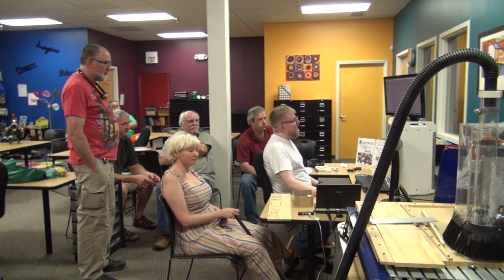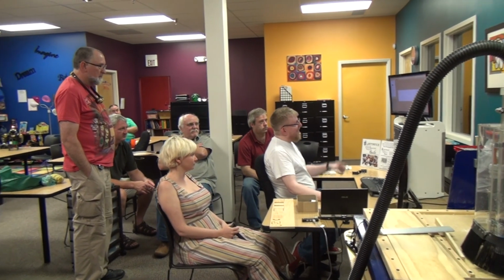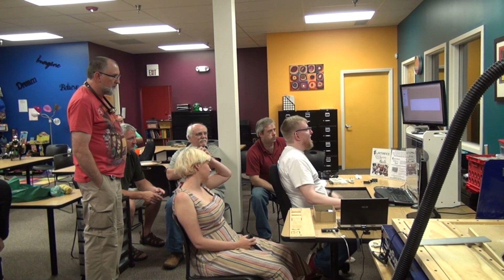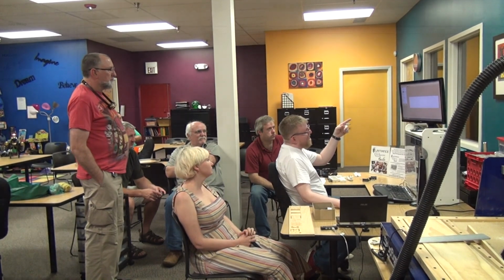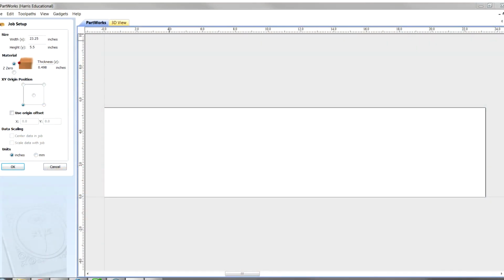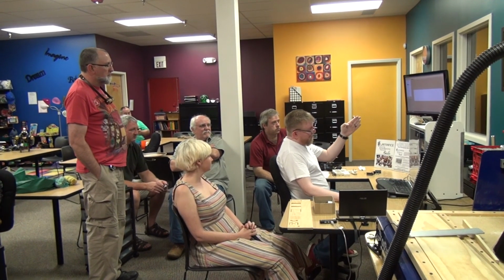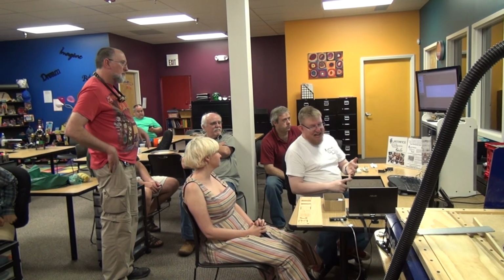Essentially, I'm going to start and create a new file. So the first thing you do is set up your job. You tell it the size of your piece of lumber you're going to work with. So in this case, 5.5 by 23 and something by about a 1/2 inch, and you tell it where the origin point is, which in this case, I want the origin here. And that makes it easy to calculate because when you place things on here, this is CAD and CAM all at once. You can design in this, you can also create the toolpaths.